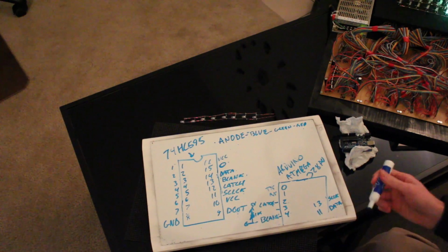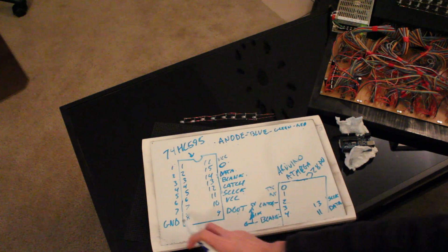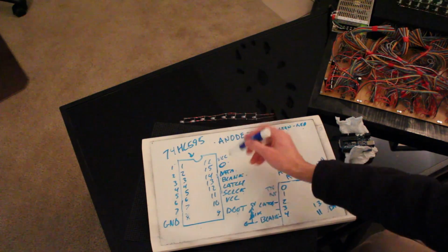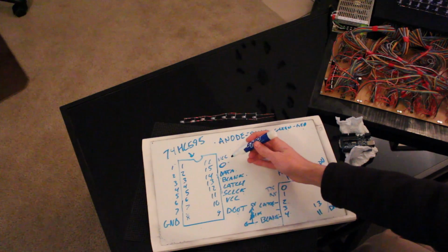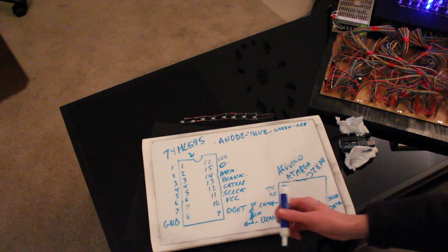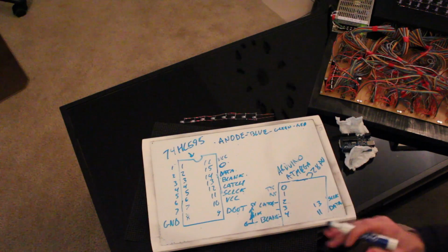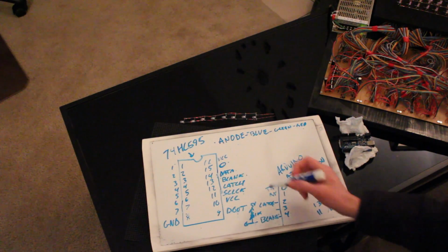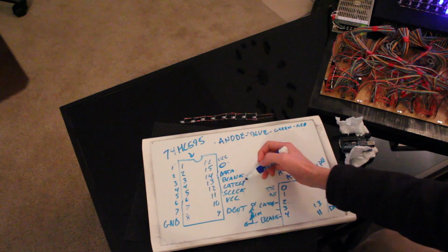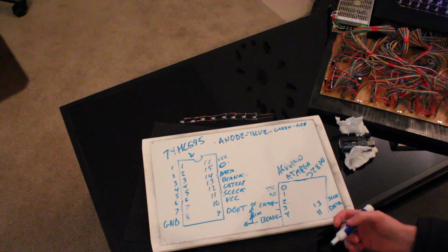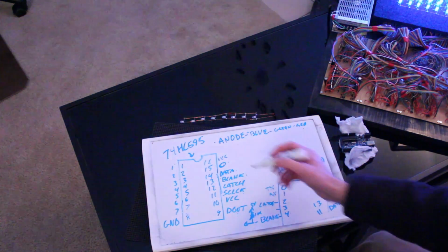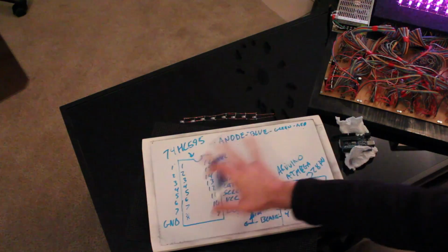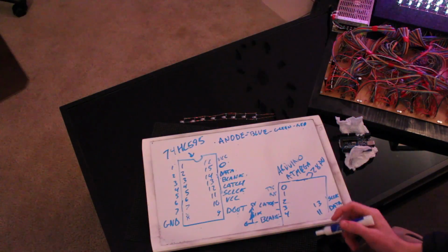Each shift register has its 8 outputs, a ground and a VCC, and this VCC should have a 0.01 microfarad capacitor to ground, just as a bypass cap to keep the supply voltage steady during all this switching. We have the data pin we talked about. The blank pin is the same thing as output enable. So anytime we pull that pin high, all the outputs turn off.